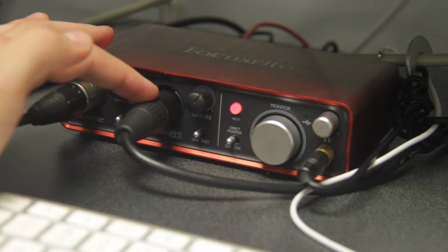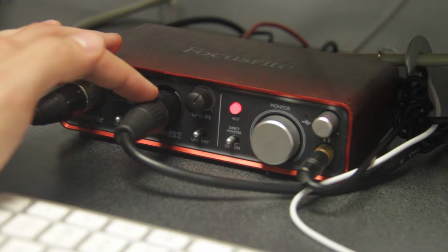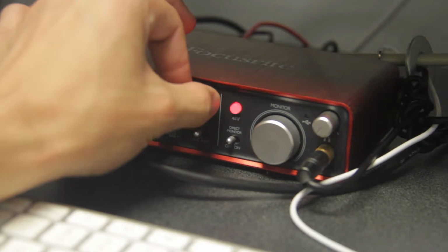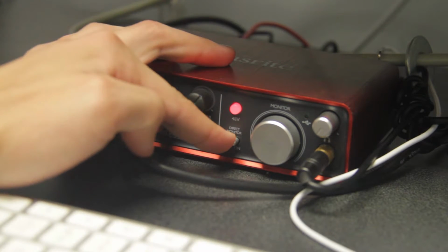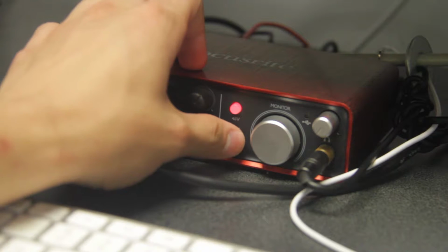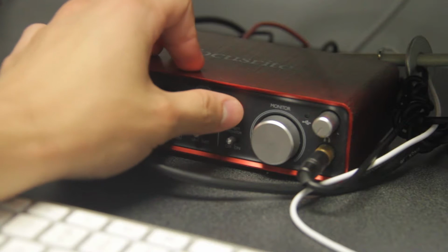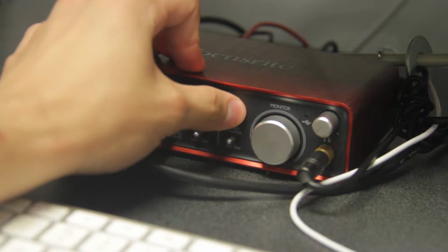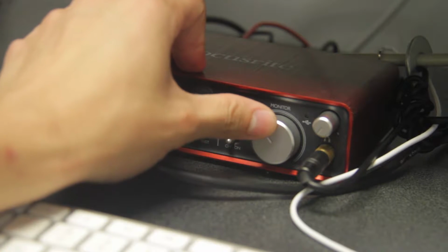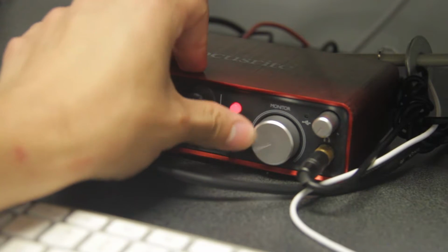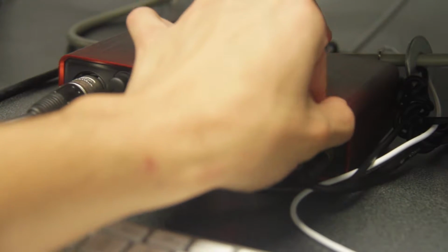It transfers the sound picked up by the mics through the XLR cables and converts it so the computer can use it. The gain switch allows you to adjust the input volume of your microphones. The direct monitor switch allows you to monitor your microphones in your headphones before recording. Turning the phantom power off will deactivate your mics. The monitor knob adjusts the output volume of your speakers, and the headphone knob does the same for your headphones.